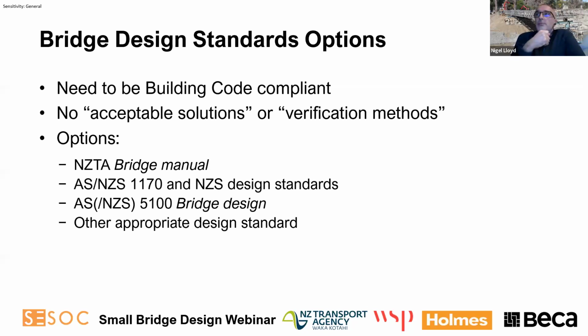Therefore, there are options that you're left with as means of designing. Principally what we're talking about here is the Bridge Manual from the Transport Agency. As Geoff mentioned, you could also take the loads from AS/NZS 1170 and use various materials design standards from New Zealand. There's the AS/NZS, principally Australian standard 5100 for bridge design. That's also just as applicable and appropriate if you can find the right section for yourselves, noting that concrete is designed quite differently in Australia than it is normally in New Zealand.